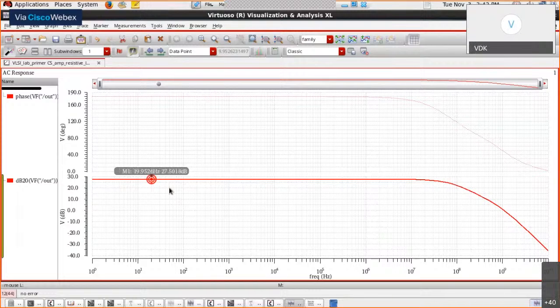That's a pretty large gain. So actually we are getting a gain larger than what we designed it for, pretty large. That is because our R out is pretty large also at the same time. Fine. Let us look at the maximum bandwidth at 0 decibels.